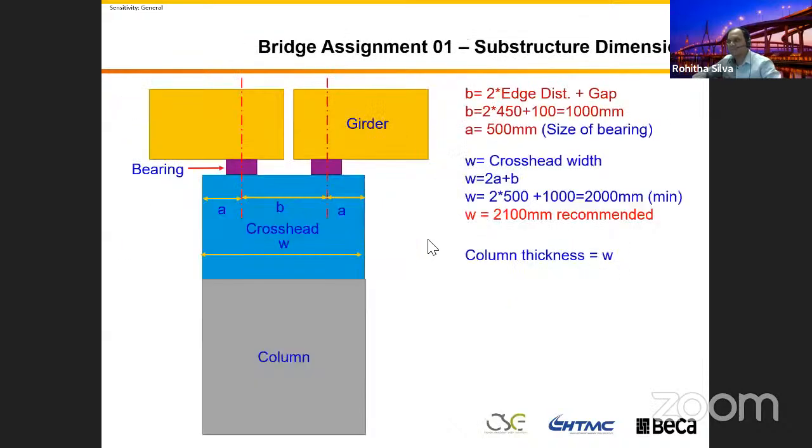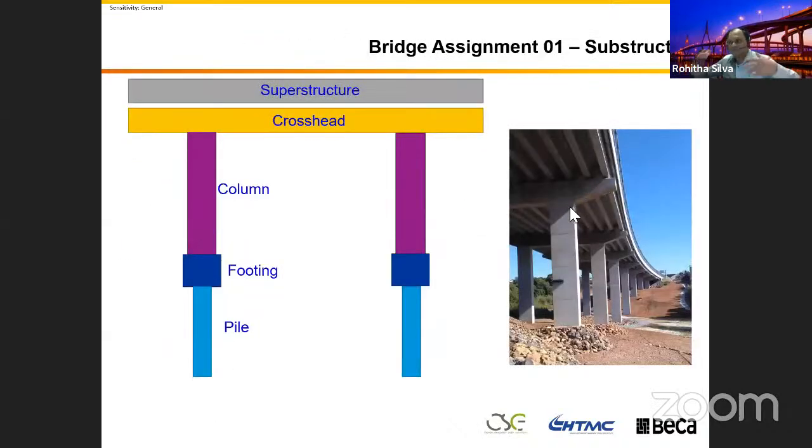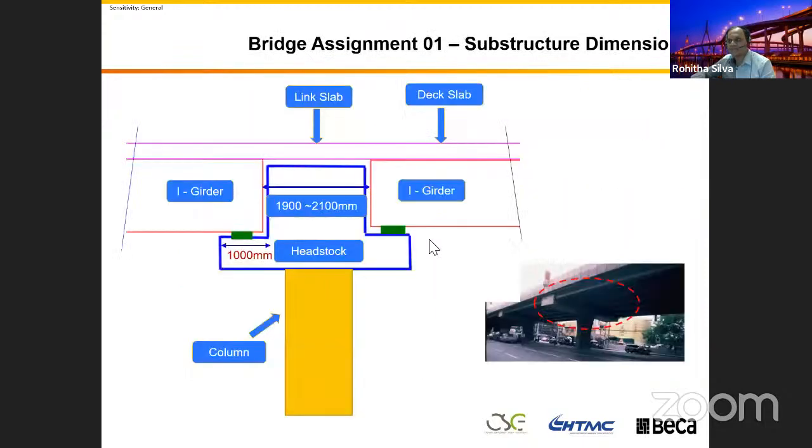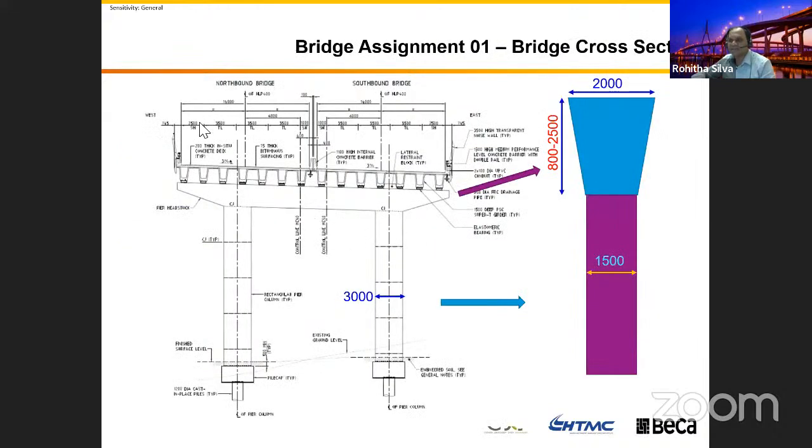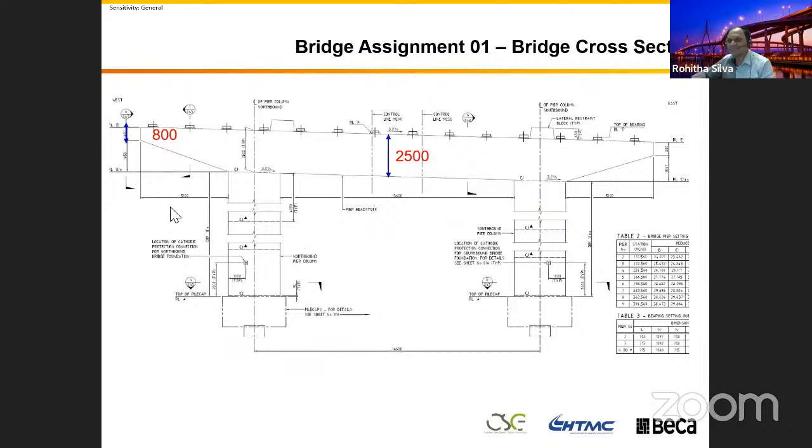You can see this big photo, right? To get the blend with the bridge, the dimension, this height and depth and everything is dictated by the architects. This cantilever length, dictated by the designers, is quite significant. It's 5.1 meters. The center line between the piers in the portal frame is 16 plus meters. This one you need to decide from a model, from the design.